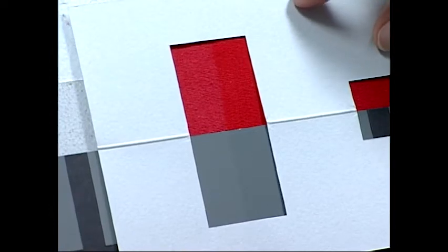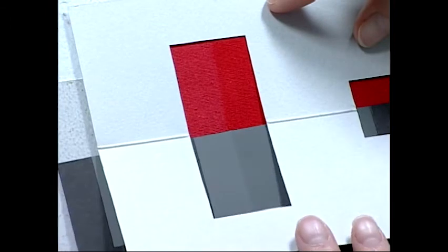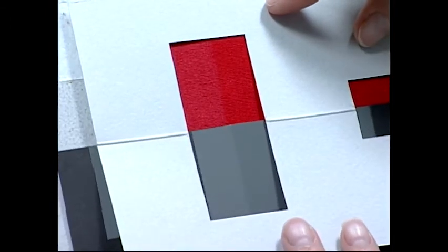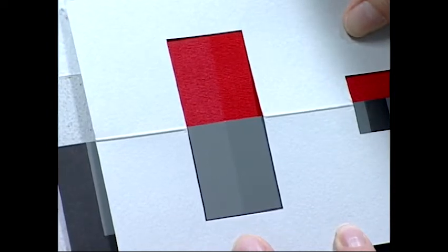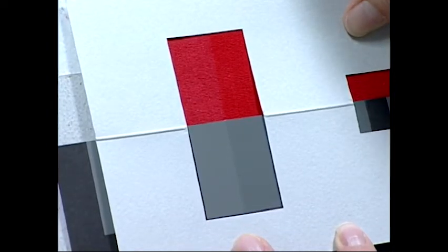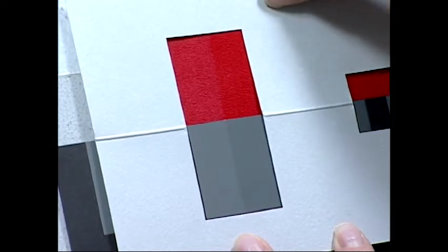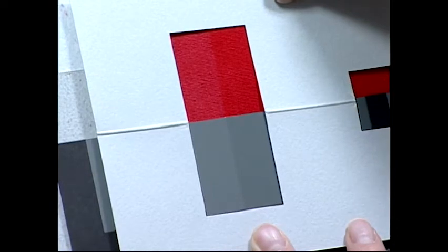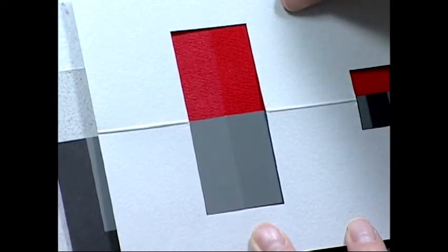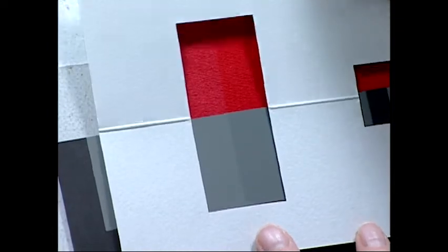The perceived visual difference between the original and tested textiles is compared with the perceived differences represented by the grayscale. The color fastness grade is that number of the grayscale tile pair whose contrast corresponds to that between the original and tested specimens. In this case, a rating of 3.5 was given. A grade of 5 is given only when there is no perceived difference in color or contrast between the original material and the tested specimen.